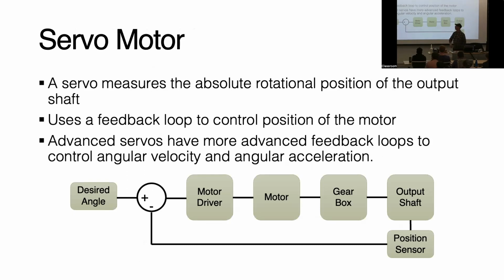All right, so how do these motors work? Well, they're invariably servo motors. Now, you can have open loop motors. People do try to make robot arms with stepper motors. There are problems with that. But usually you want to know where your arm is, so you want the feedback. So a servo motor is basically just a motor, right, with maybe some gearbox to translate rotational speed to higher torque, okay? So you move faster, you go through a gearbox, you get more torque, but you move slower. You're trading speed for torque.